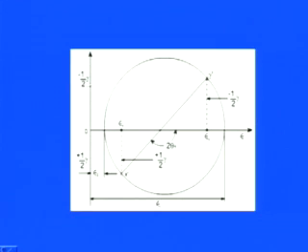Measure the required parameters, and also whatever angles are there. So here you see all this. You have epsilon x, the normal strain component in the x direction. On the y direction, you have minus gamma xy by 2 and plus gamma xy by 2, on both the plus and minus sides of the y axis. And then you need to draw the x dash and y dash components. So this is x dash 1, this is y dash 1, because you have the coordinates in terms of the strain components. So once you plot those, join this line.